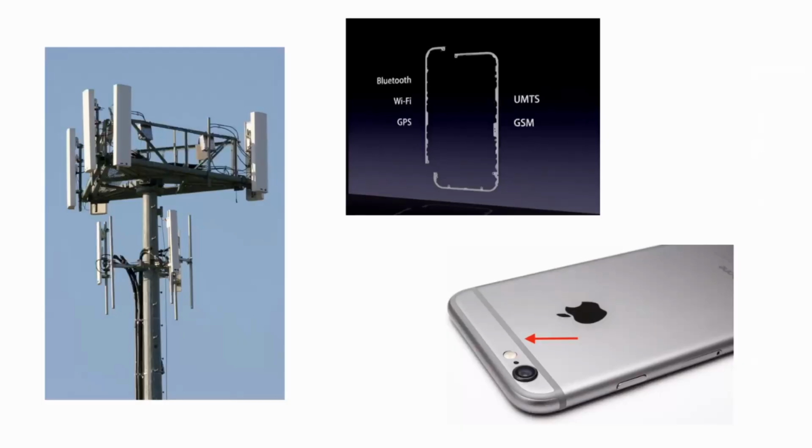5G is like 900 megahertz. There's different frequencies for these different things, right? But your phone, with the antennas in it, is able to figure out, is it Bluetooth, is it Wi-Fi, is it cellular, based on the tuning of the different frequencies. And what's more, it gets way more complicated. To keep the calls secure and to make sure that multiple people can be talking at the same time, your phone will do something called frequency hopping or spread spectrum hopping, where multiple thousands of times per second it will switch from one frequency to a different frequency.